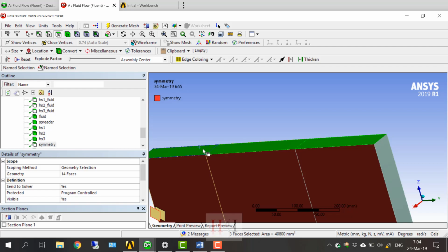If you set the pressure equal to 0 gauge, constant, you will find the flow going down here without any effect, without even putting any heat from there. The flow is going down due to gravity, and you are assigning a constant pressure here, which is abnormal. So you must define a pressure varying with height.